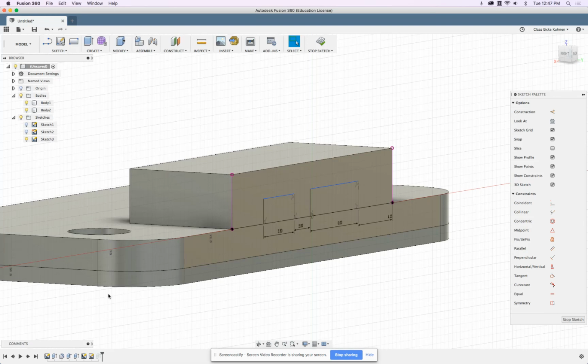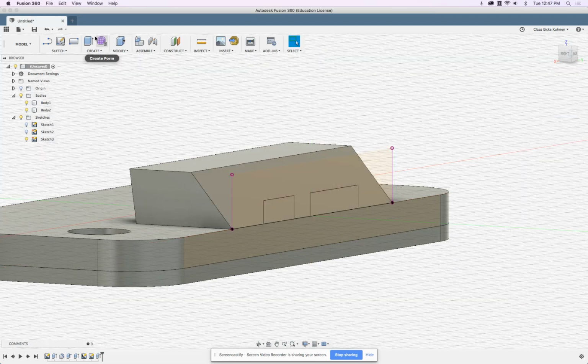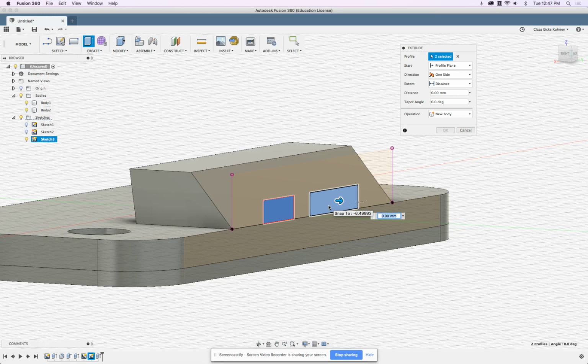So let's see, what's the top part? Maybe 2 millimeters. So dimension this point to there, that should be 2. And horizontally aligned this point to there. So these two rectangles are at the same height. Very good. And then these two we just push into that surface by a distance of 8. No, that's too much. 5 millimeters, so -5.